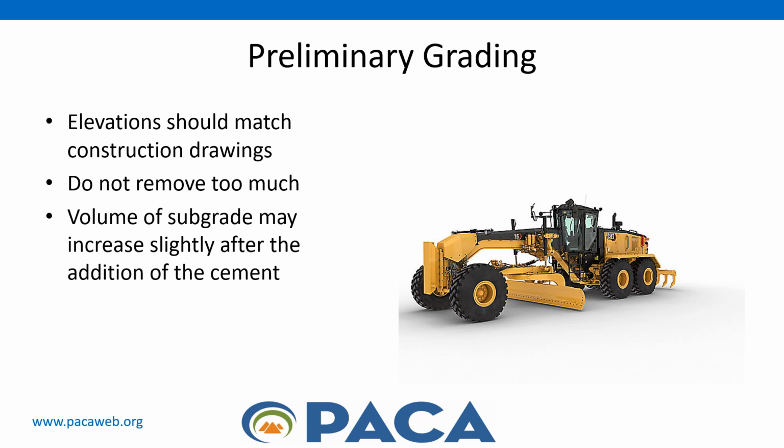The grade at the start of the mixing should be similar to the final grade after mixing. However, it should be taken into consideration that the volume of the subgrade, and therefore the grade elevation, may increase slightly with the addition of the cement.